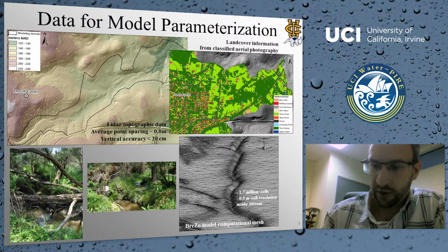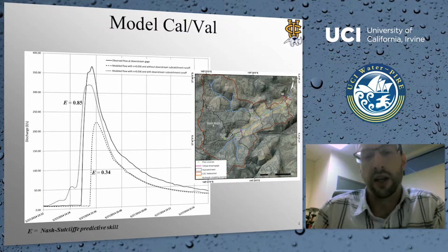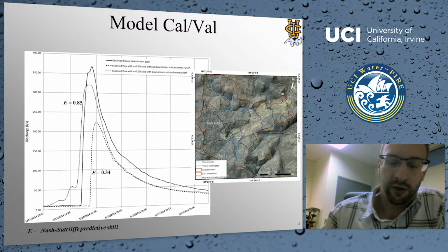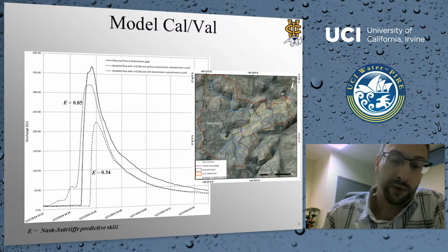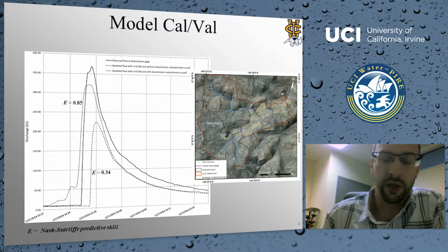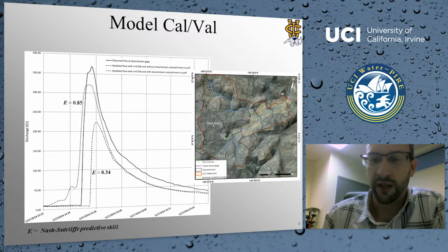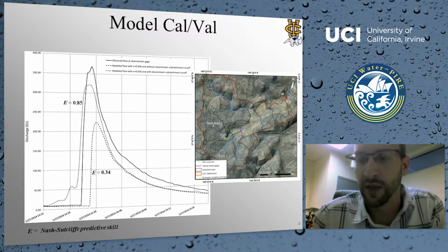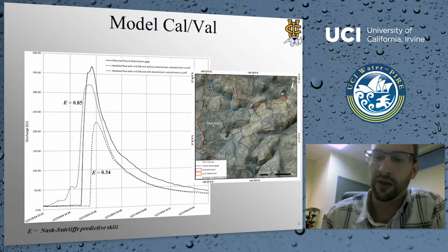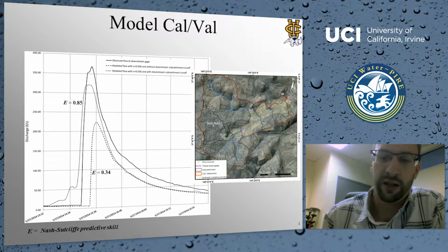All right, so moving on to the fourth slide. We validated the model to flow that was measured from an actual rainfall event that occurred in May 2014. Our initial attempt to validate the model didn't go that well. What we did is we injected flow that was measured at the north trip, the central trip, and the south trip that you can see in the right-hand side figure into our hydraulic model.